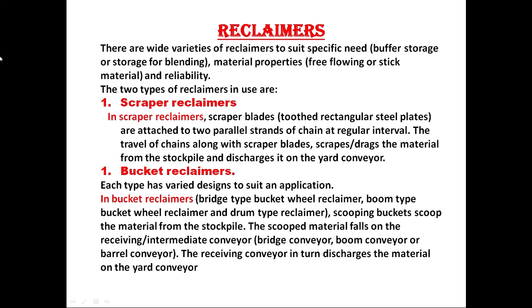The second type is bucket reclaimers. Each type has a varied design to suit the application. In bucket reclaimers, scooping buckets scoop the material from the stockpile. The scooped material falls on the conveyor, and the receiving conveyor discharges the material on the yard belt.